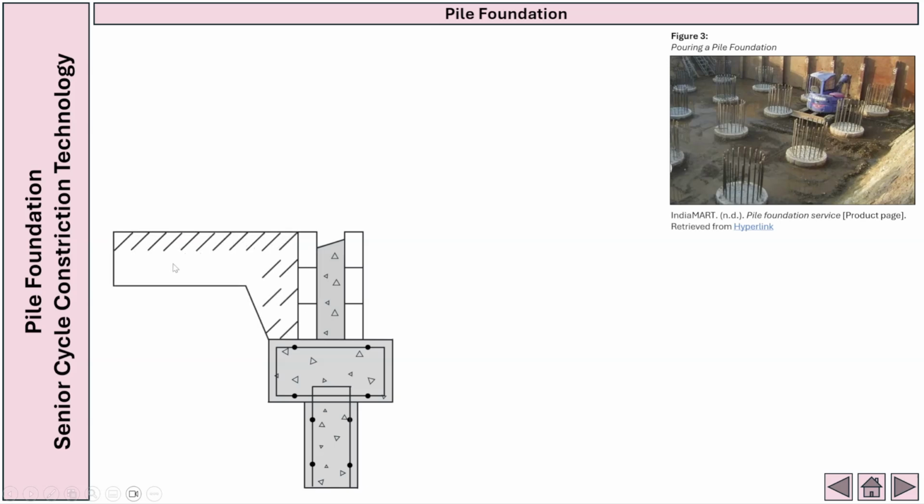On the left side, we're going to go outside the building. So this is going to be our ground layer here. This is the surface that you walk on when you're outside. And all I've done here is I've gone up 300 millimeters and brought it across just over here and then connected it using the 60-degree set square. This is ground surface here, indicated by these lines. You don't need to fill in the whole thing.